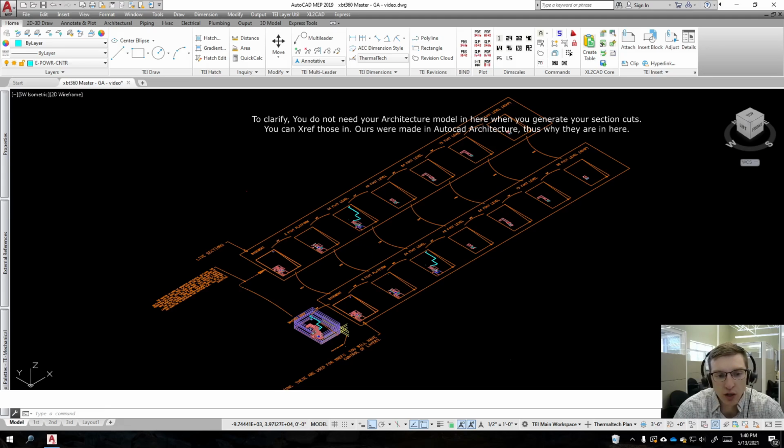You've got that 3D entity that will be displayed when you are in 3D ISO mode. As soon as you go to top down, left, front, right, or bottom view, it's going to display a different block instead. So you need to be able to edit all of those blocks in order to use multi-view parts. It can become quite the hassle.